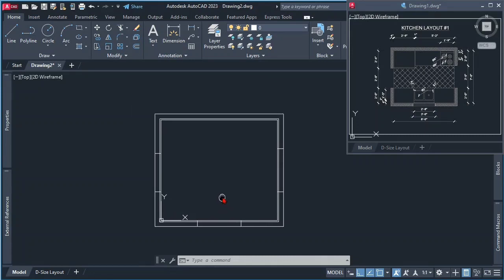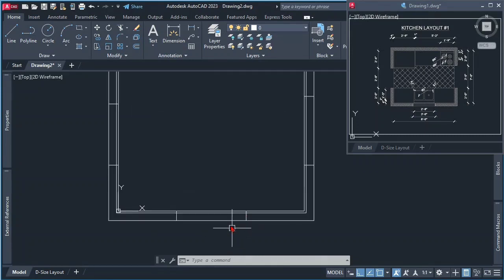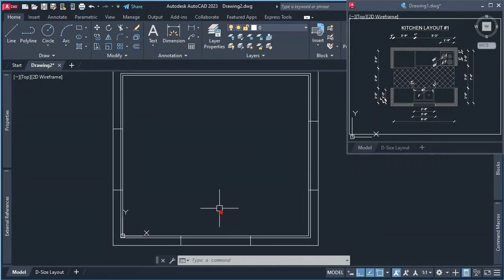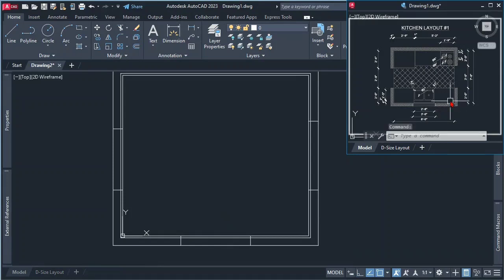All right. So that's one of your first tricks in AutoCAD, how to move things exactly from the middle when you don't have a dimension or a distance. All right, so let's keep moving. We have this opening, this other opening for the window, and this other opening, so we completed all of our openings.